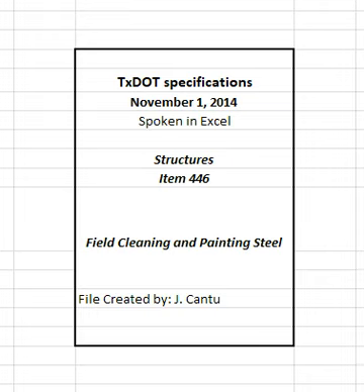Clean and paint unpainted areas of newly erected steel, including bolts, nuts, washers, and areas where the shop-applied paint has been damaged or fails to meet specification requirements, in accordance with the method required under the paint system specified and Section 446.4.7.3.1, General Preparation. Water blast exposed surfaces of all newly erected steel. Provide tool cleaning surface preparation to all repair areas.